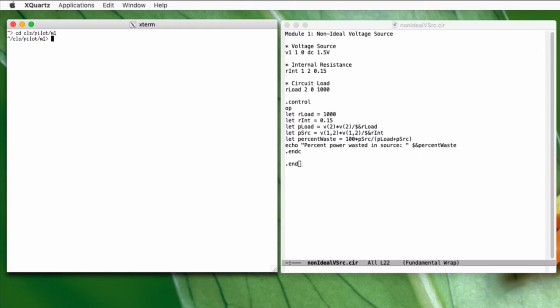The other thing is the circuits that we're going to be dealing with in this class are quite simple. And so writing a netlist by hand is not particularly difficult. You really need to resort to the graphical simulators when you've got larger circuits that contain hundreds of elements potentially. So the simulator that we're working with then is called NG Spice.